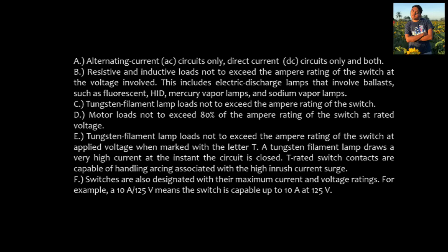B. Resistive and inductive loads not to exceed the ampere rating of the switch at the voltage involved. This includes electric discharge lamps that involve ballast such as fluorescent, HID, mercury vapor lamps, and sodium vapor lamps. Yung resistive loads po ay pwedeng ma-convert yung electrical energy into heat. Yung inductive load naman po ay pwedeng ma-convert yung electrical energy into magnetic energy. Sample po ng inductive load ay electrical motor.